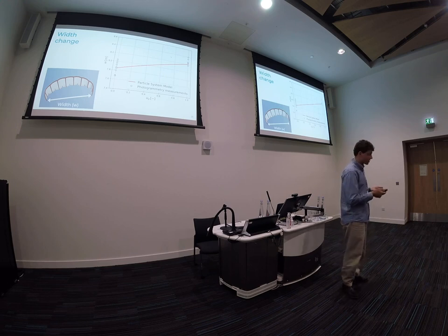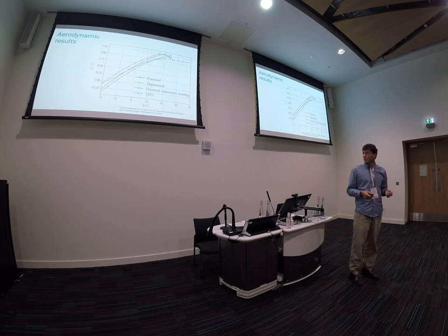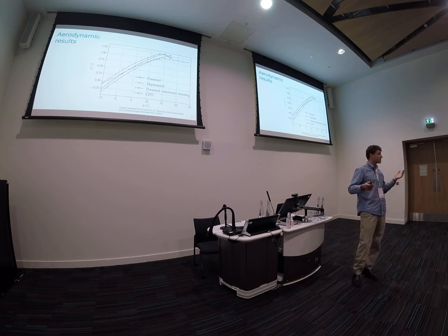You can also look at the aerodynamic coefficients. I just took the C_L-alpha plot here, where we see that there's a difference between the kite's powered state and the kite's depowered state, as one would expect. And it's also plotted next to CFD results to see if it's approximately in the same ballpark, and yes, it is. So that's nice.